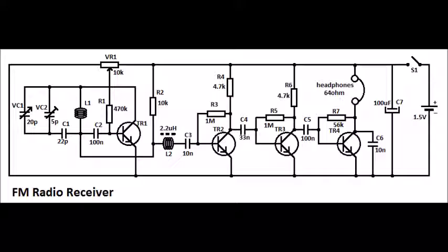So what we do is we take the signal from the local oscillator and pass it through the mixer along with the signal from the antenna, so that the required signal that we need becomes 150 megahertz. So on passing this mixed signal through all three filters subsequently, slowly removes all other frequencies which act as noise in our case, and finally what we have is the signal that we require at 150 megahertz, which is then decoded and sent into the headphone.